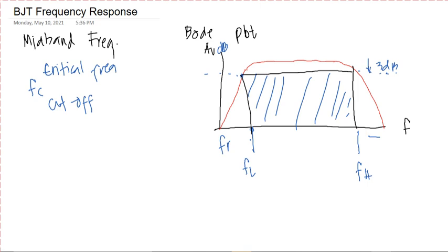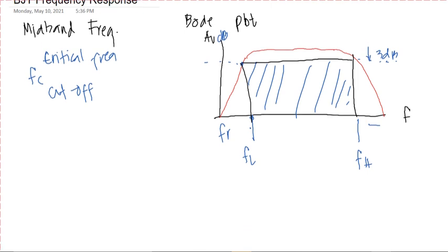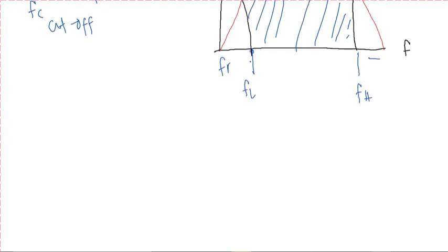Because we will be talking about the frequency response of BJT amplifiers, what concepts do we need in order to better understand this? Take note that we need the concept of DC. We need to solve using DC because that is where we get our RE. Remember that we can get beta RE and also beta IB using our DC analysis.